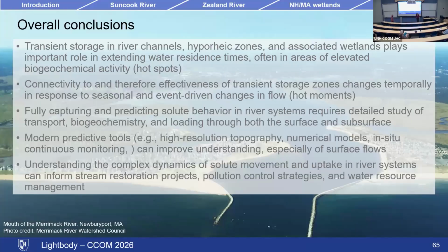to a concentration. For salt, we often use conductivity, which again you need to calibrate. So we're often doing a derived metric and then calibrating that to get a concentration. And that gives you information across the cross section where you measure it. The idea is that you're measuring downstream of where it's mixed across the cross section, so it doesn't matter whether you're measuring on the left or the right.